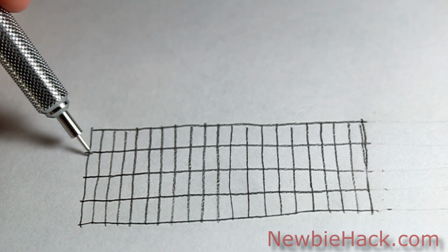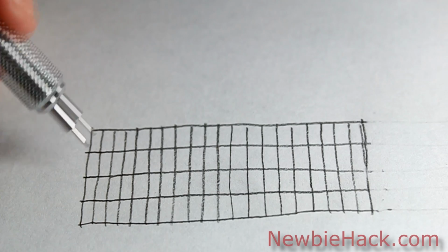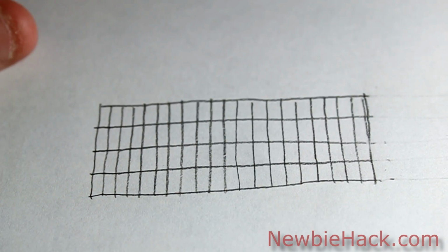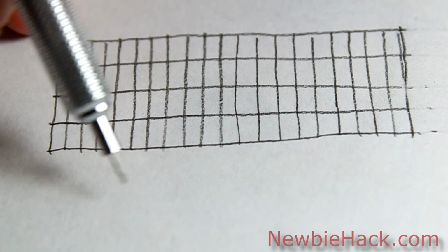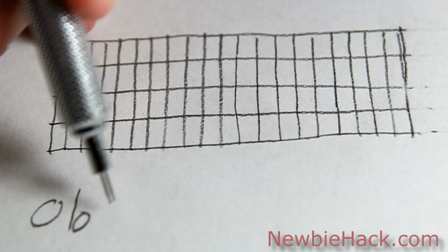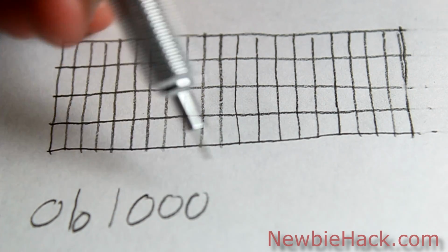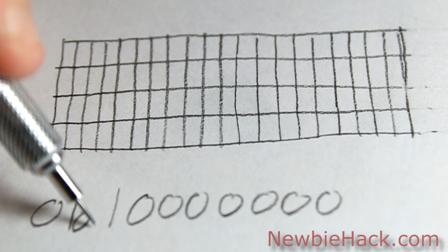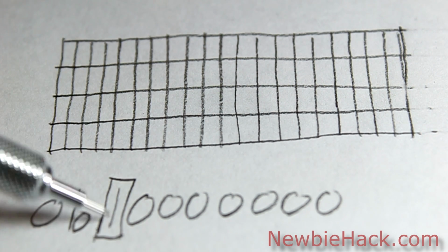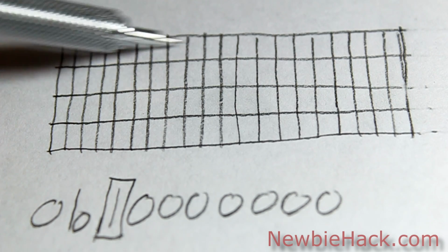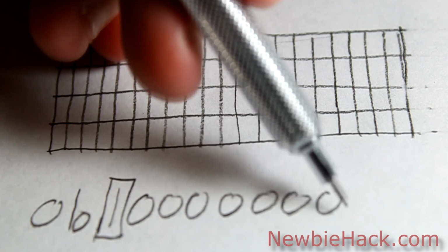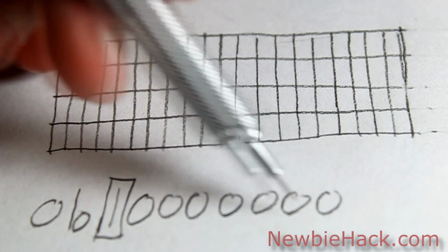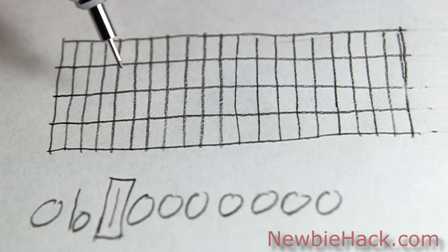Each of these rectangles that make up the LCD contains actually a number. And there's a command in the LCD that we can use, send a command function. The actual command is represented in binary, starting with a 1, 0, 0, 0, 0, 0, 0, 0. So this 1 in the 8th place allows you to access these specific locations on the display. The remainder, or the remaining zeros here, can be a number, and that number will represent which rectangle you're going to be setting the location for your cursor.